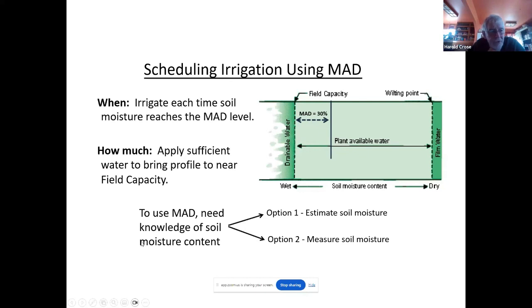Let's take wheel lines, for example. Take a 30-acre field. And a wheel line, if you have one wheel line on that field, will irrigate, let's say, 2 acres on one wheel line. And your irrigation frequency is 3 days, and you got 10 acres, your system can only get across that in 5 days. You'll have to put another wheel line on that field to meet that irrigation frequency. So if you have one wheel line on that 10 acres, it'll dry. By the time you get back to irrigate again, you're already putting your plant in stress. And if you put 2 wheel lines on there, you can meet that irrigation frequency.